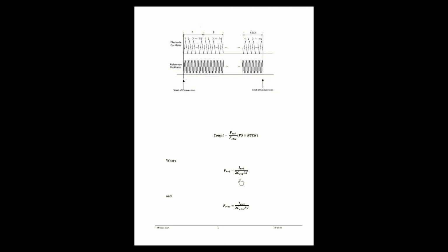And the reason for that is because it allows us to have a really high frequency here. We're going to have a lot of counts in here, which means that we don't have to scan as long to get the full count. So by setting this reference frequency to a large value, it decreases the time it takes to scan the touchpad. Now, it all depends on the capacitance of our touchpad. We may not be able to do that with a different touch sensor.